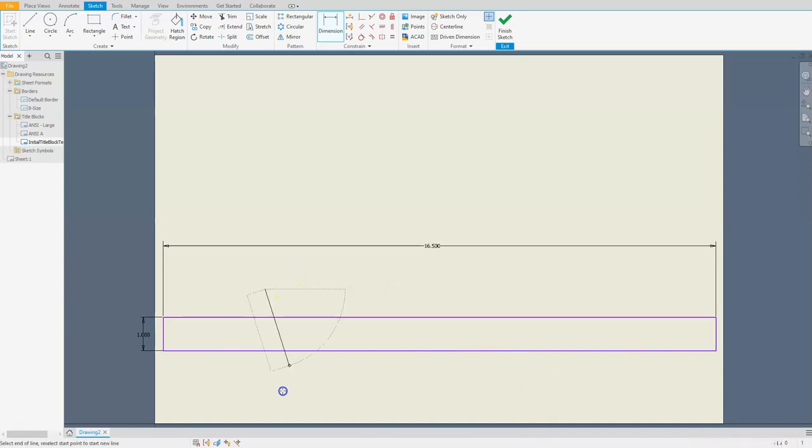So I'll go with a line. And I'll make sure that those lines are vertical. Remember that you can use constraints at the top if you don't make it vertical. So I'll make this last one a little sideways. And what I mean by that is that you can always straighten it up by using the vertical constraint and selecting the line. Okay, the next thing I want to do is I'm just going to go ahead and trim off the bottom portion of this by using the trim command. So I'll trim the tops and the bottoms.